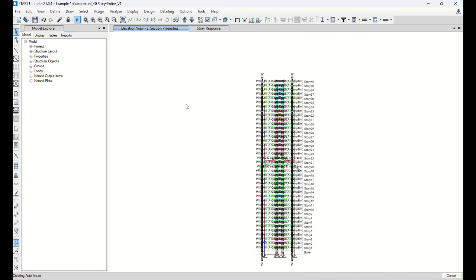At this point, we only draw two outrigger trusses on grid line B and grid line E. This should be based upon your model, so you can find out which grid is really lined up between your column and wall, so that the outrigger should be straight.